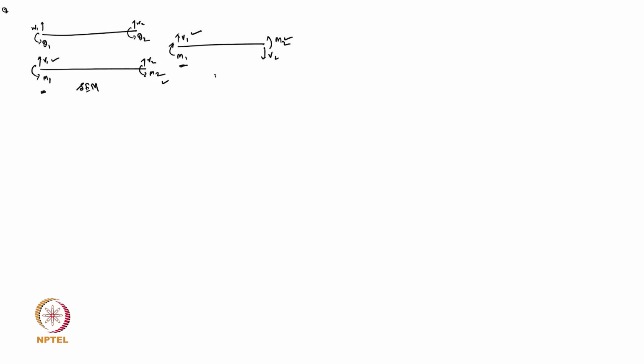So once we have it in transfer, that definition of M1 on the left hand side and V2, the shear force at the right hand side, need to be altered. Don't forget that. If you forget that, your signs and everything will go wrong. You will not get the solution properly. So this thing we have to change. Once you are converting from transfer to spectral, you have to alter that sign also.